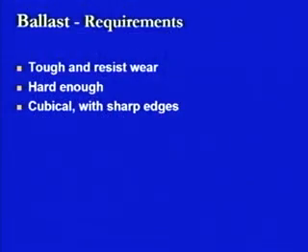The resistance to this abrasion is defined as hardness, and the ballast should be hard enough so as to resist this type of action. Then another one is that it should be cubical or it should have sharp edges.